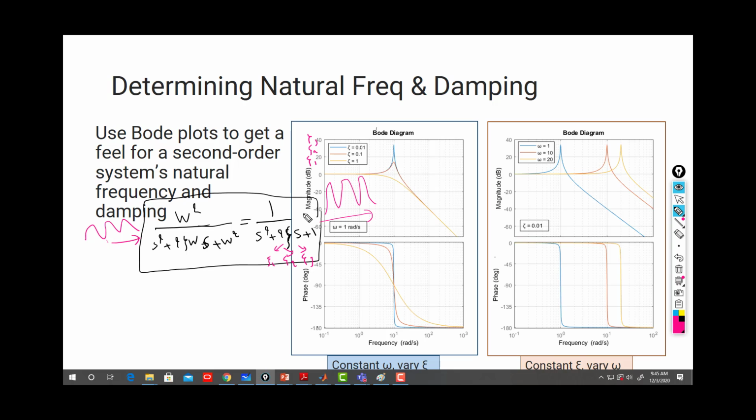That's a frequency analyzer. That's what I'm recording, the Bode plot, which is basically the ratio of amplitude between the output and input, which is what we call the magnitude. So I'm drawing it for each and every frequency, and I'm drawing the phase lag between the output and input for the given system, and I'm getting it this way. So the omega here is the omega of the system, but omega here is the omega of your input.